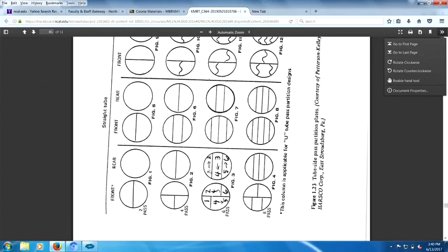The orientation on this doesn't matter. Let's take this one right here. This is a 6-pass. These are channel covers. So it goes in at 1, comes out at 1, goes into 2 because it's the only place it has to go.